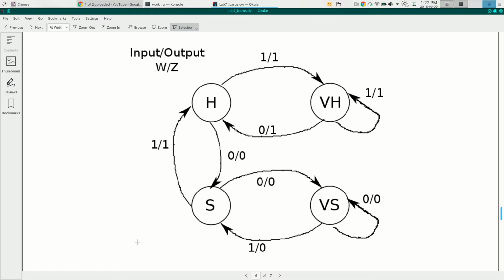And we've got 4 states. And we know state machines are clocked on a clock edge. So something like always at positive edge clock, begin. Well, in words, what do we want to have happen here when the clock ticks? We need to know what state we're in. And based on that state and on the value of the input, we want to set the value of the output and the value of the next state.